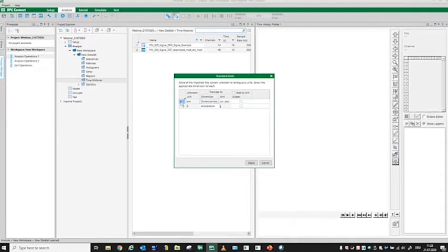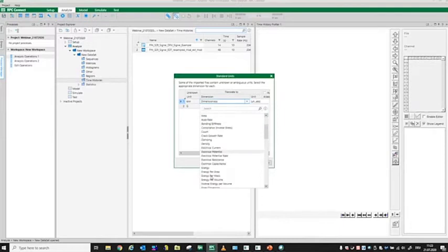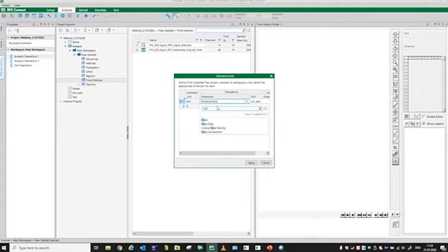So in this case, I know kilonewton is a mistype, and I say, okay, it is a force. And I can use the filter function, say force, and of course kilonewton refers to kilonewton. If I know that I always make the same mistake, or I have Newton meters always with an X in between and not with a point, you can tell RPC that it applies, and it always does that when using the import function and finding files with this similarity.